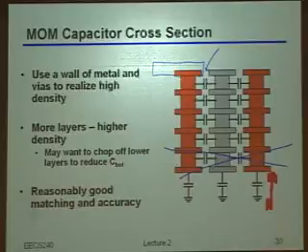Yeah, so the density I get per unit area, because I chopped off those bottom layers, is lower, right? So the question is, what hurts more? Does it hurt more to lose that density? Or is it better to have a thicker spacing away from the substrate? And obviously, depending upon what the actual values are, you may not know a priori which one of those two is the right answer. And again, this is actually a homework problem that you may get asked, or an exam problem, at some point. Okay?